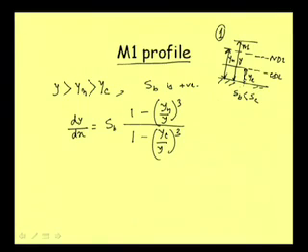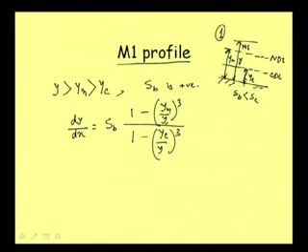Well, with this relation, how can we see the characteristic? Well, first we need to know whether the profile will be a rising profile or a falling profile. So now let us see that when y is greater than yn, yn by y will be a fraction, and its cube will definitely be a smaller fraction, and fraction means it is less than 1. So 1 minus something less than 1 will be a positive term, that is, our numerator is positive here.